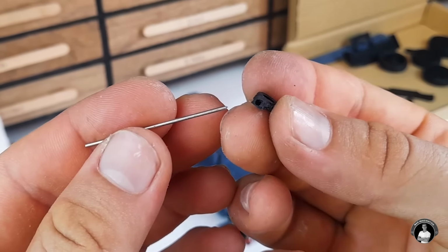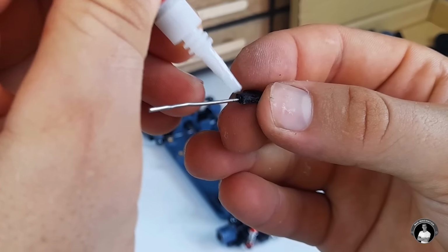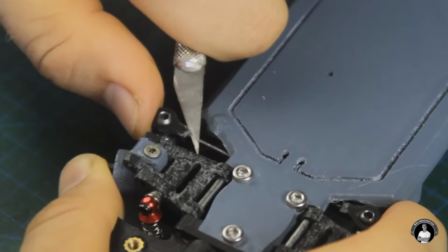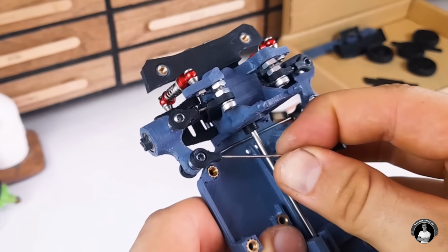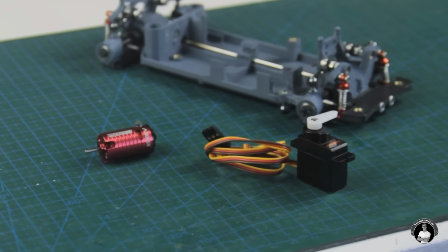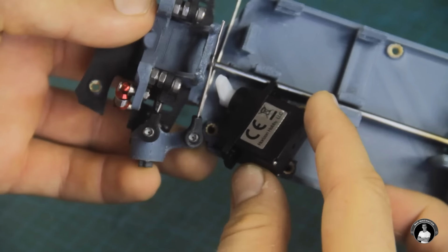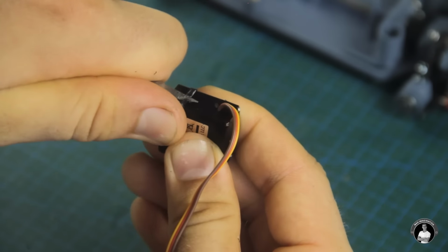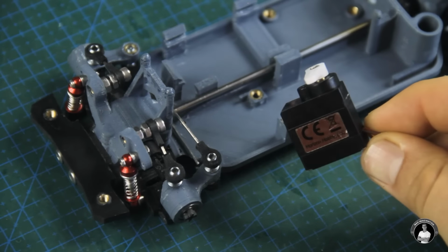With some paperclip wire, we'll make the servo link, which clips onto the only ball screw sticking up. Now comes the time for installing motors. Starting with the servo motor, since the stock Metal Gear servo doesn't fit into the chassis, we'll need to clip off the 2 tabs to then make it fit.